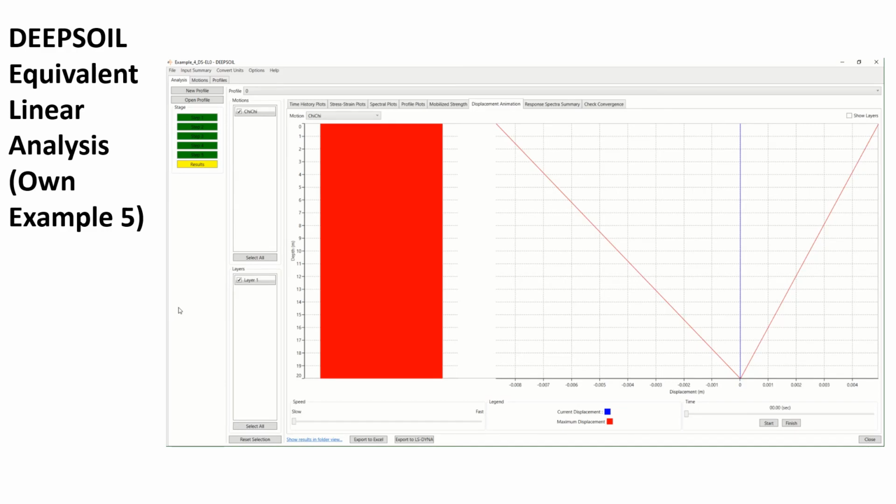One way of knowing that is to know the shear strain to which the soil is being subjected as a consequence of that seismic motion. As you can see here, the maximum deformation experienced by the soil will be around 0.008% of shear strain. If you remember that graph of the shear modulus versus deformation and damping ratio, it would change at, let's say, medium to high shear strains. So by the input of this seismic motion, the Chichi earthquake, the properties of G and damping ratio are not altered or modified as a consequence of this seismic motion. So that's the reason why equivalent linear analysis and linear analysis are going to be the same.